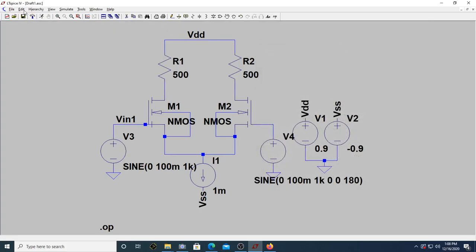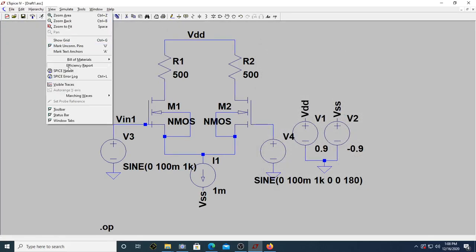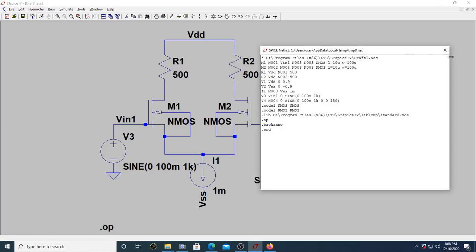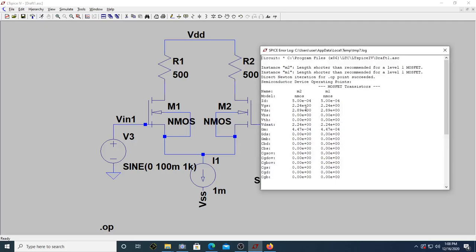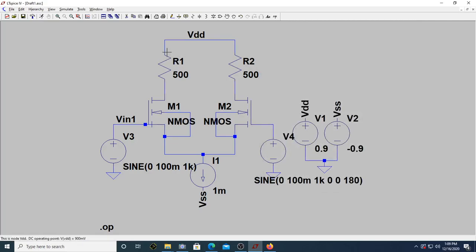So let me just see, can I see this netlist. Okay, what I do is I just go to here, you can make out. So you can see the VGS is actually 2.24 volts. Okay, oh sorry, why I'm not getting it is I have not defined the model file, because of that I'm getting 2.24 volts, which is not possible here.